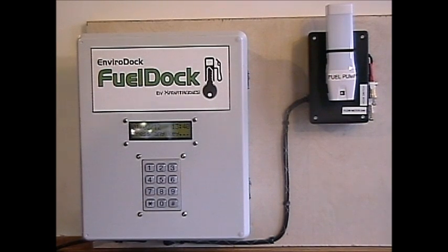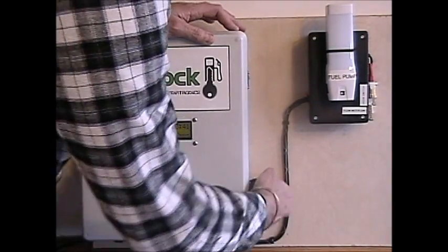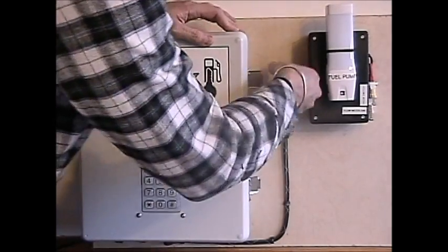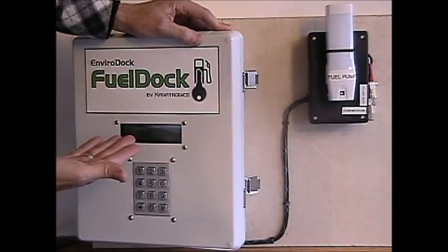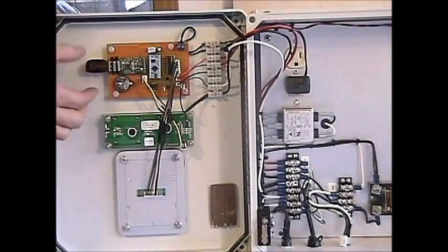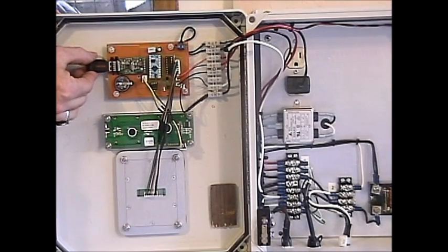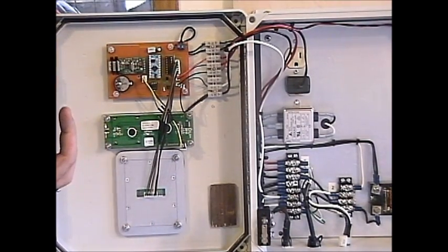When the site administrator is ready to retrieve the data from the system, operation is quite simple. He would unlock the hasp that is over here and release the 2 latches. There's an automatic power interlock, so as soon as the cover is open, just an inch or so, it drops power to the unit. Then see on this card right here, there is the USB memory stick data logger. This is removed just by pulling it out.